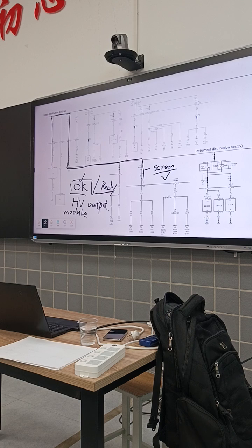So the DC is after the HV. Yeah, after. The HV outputs to the DC and the DC converts, because the DC is taking power from the HV. So that's why it was able to start. It showed the OK sign, but gradually the battery was reducing. That would have later created another error sign because the battery is going to drop a little bit more.